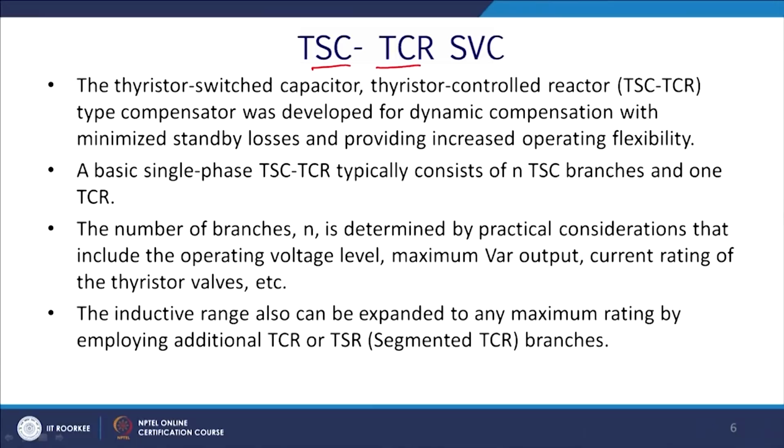Now, you may have a TSC-TCR combination. So, then you will also have a thyristor switch. So, it can manipulate turn on and turn off, as well as you have the TCR. So, thyristor switched capacitor and thyristor controlled reactor, TCR, are the types of combinations.